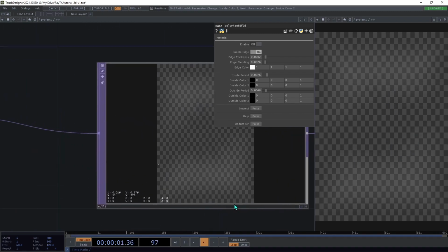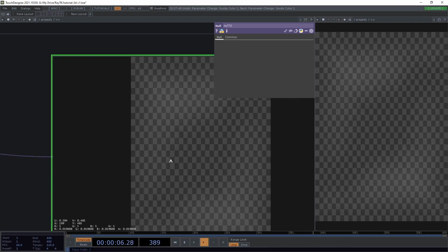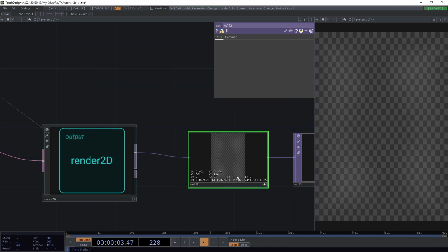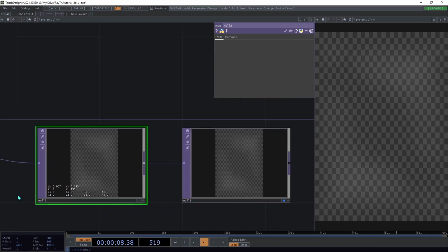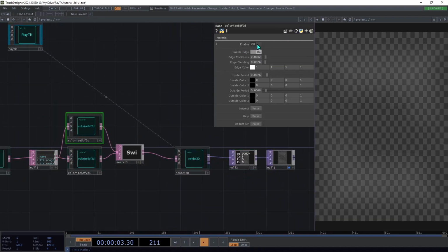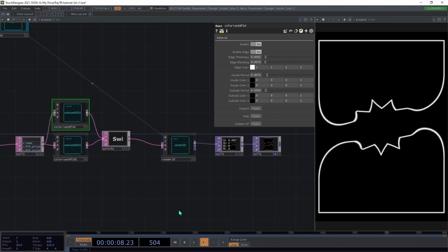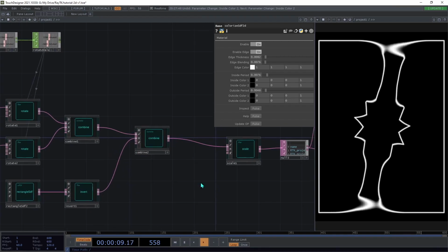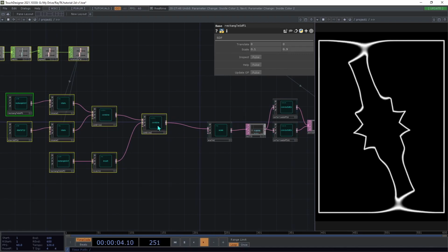distance values. And if you look really closely in here, or use display pixel values, you can see the outline of the shape, but because it's just raw distance data, it's not in a range that's easily visible. So that's why this Colorize SDF 2D is here to convert that into a visible range. So we've now got that scene set up, and we're going to start playing around with some more filters.